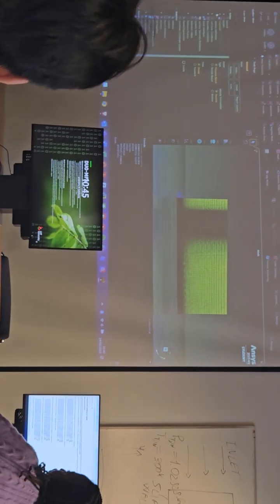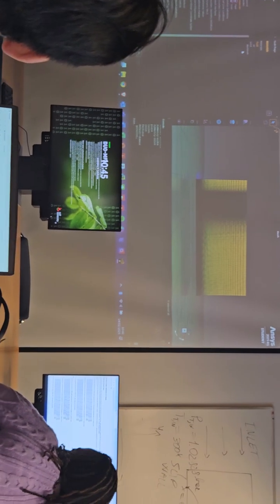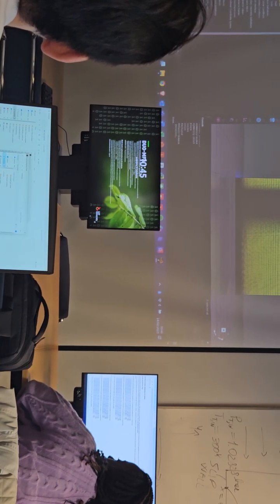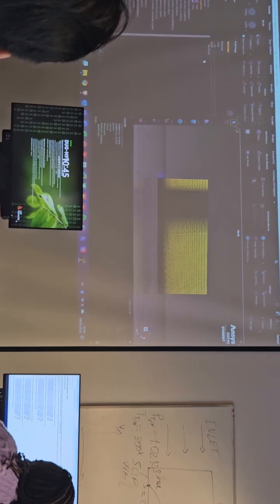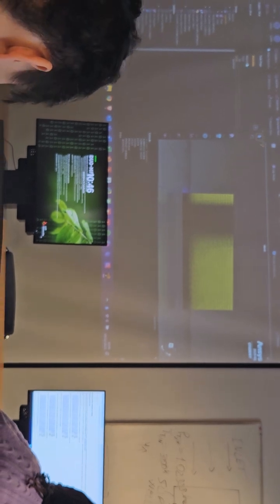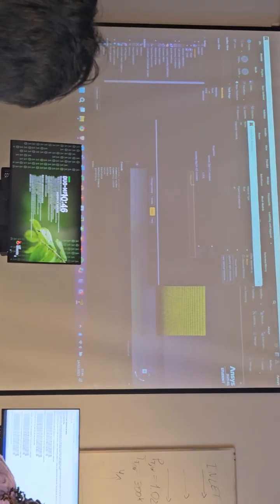So I go in materials. If I double click on materials, I'll get here the materials for the fluid, that is air, and the solid, that is aluminum. We don't have any solid part. I mean, we have the plate, but we are not really solving any equation for the plate. So we are just focusing on air. If you double click on air, right now it's set as a constant density and constant viscosity fluid. So like the simplest way to model air.